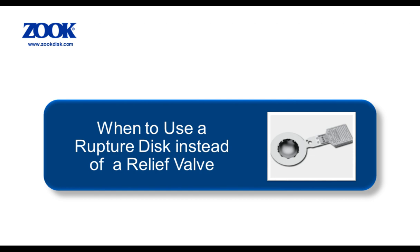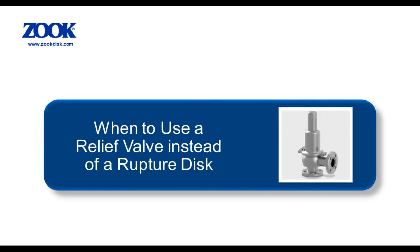Second is leak rate. Valves by their very nature can leak, which can be a problem in some services. Rupture discs, however, are virtually leak tight. They are basically a solid barrier with leak rates at the molecular level. The disc is very fast acting and, unlike a relief valve, does not require a change of direction for flow to take place. There are no moving parts in the disc, so reliability is high. There is no way to adjust the disc setting, which makes it tamper-proof.